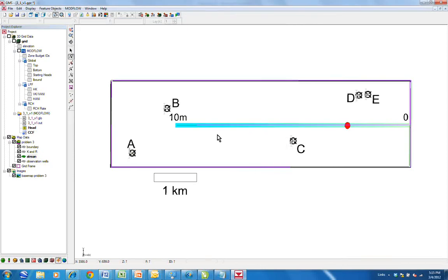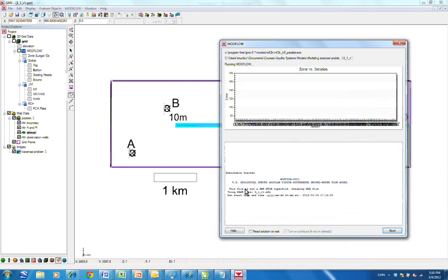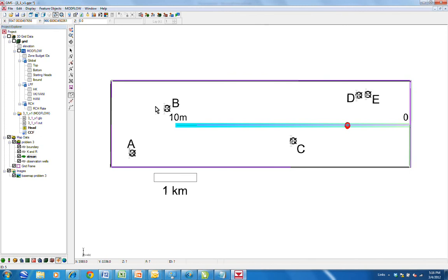And we'll also want to go in here to create a point, put a point right there. What that's going to allow us to do is calculate the flow for each one of the reaches. So if we go and rerun this, what we see now is if we click this, I can select an arc. When we select that arc, it's selected right up to that point. That's the reach that we're interested in.